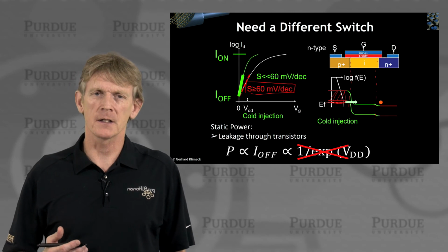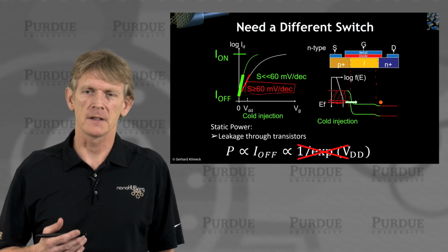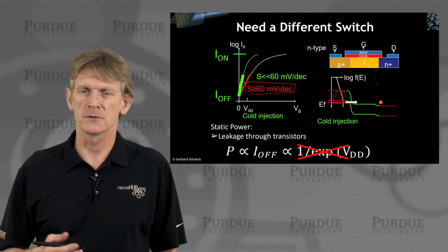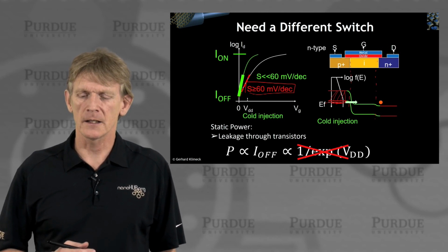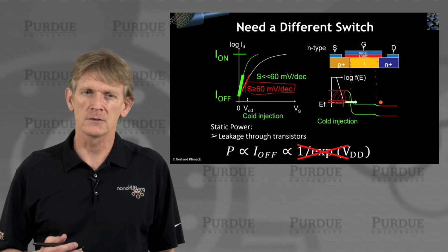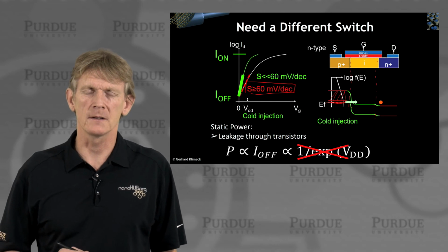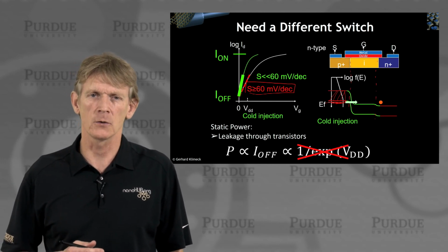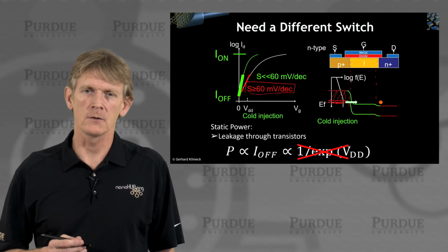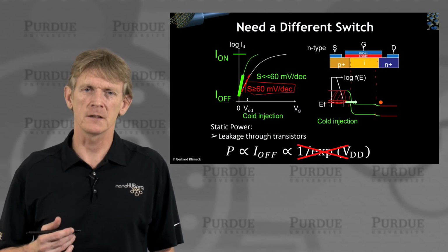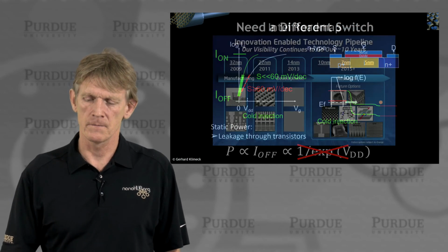There's another candidate out there that looks quite promising as well. That's the NC FET, the negative capacitance FET. So I'll invite you to study that as well and get some overview. This tunneling FET, the tunneling device, is actually very hard to build. Electrostatics are complicated. You really have to understand how these bands move, and then there's band tails. There's all kinds of complicated things going on. And it may not happen. That's how it looks right now. In 2020, there is no TFET in sight that is going to make it into production. But at least conceptually, it looks pretty easy.